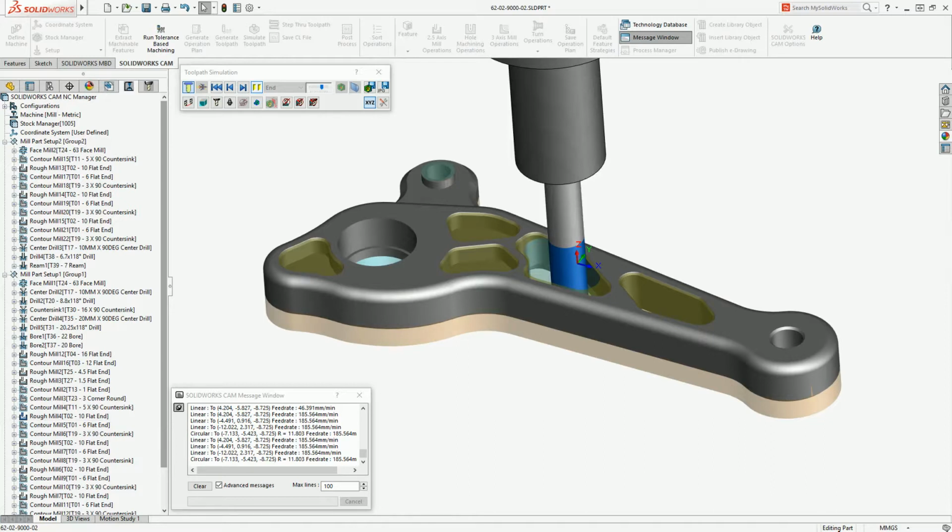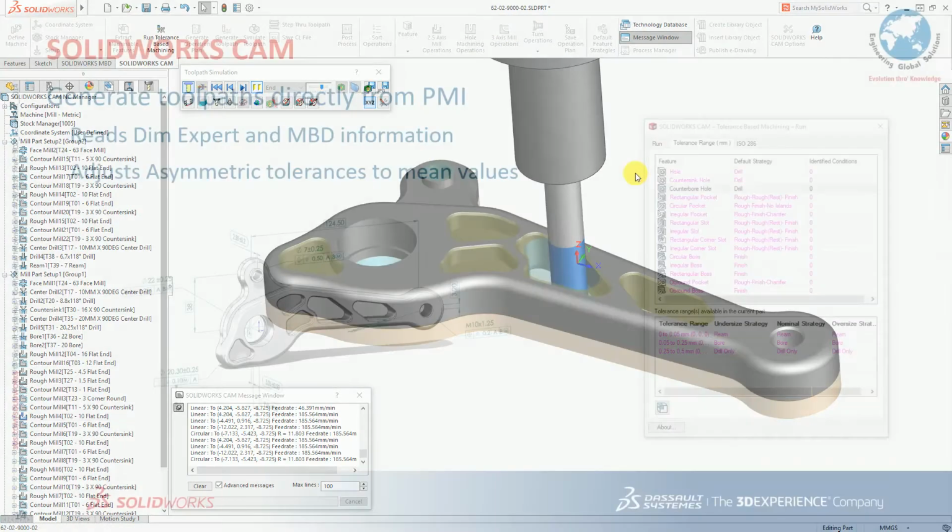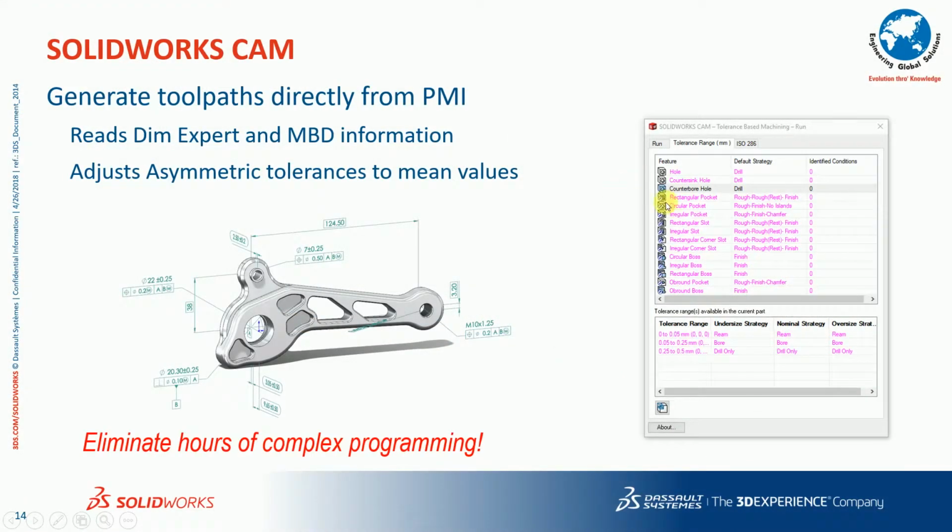So this is the SolidWorks CAM user interface. Once you have done the model, you can extract all the machining features. Here you have one more advantage called automatic feature recognition, which will recognize all your features without any data loss. Right, so once you have done all this, at the end you can generate the post processes, the operation plan for your entire machining operations, and that will give you the G code and M code for your machining operations.